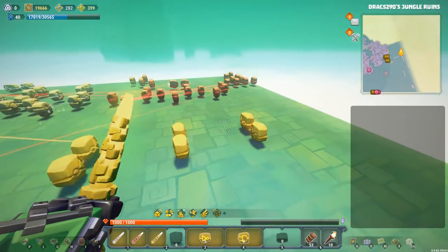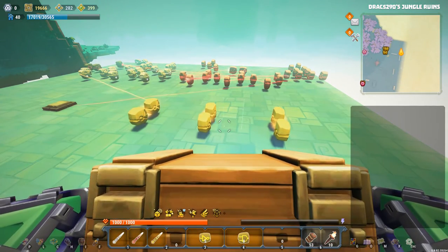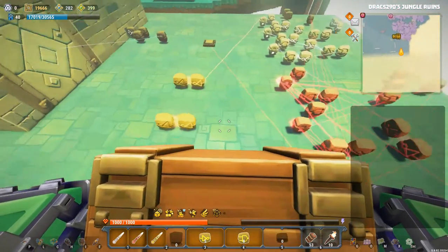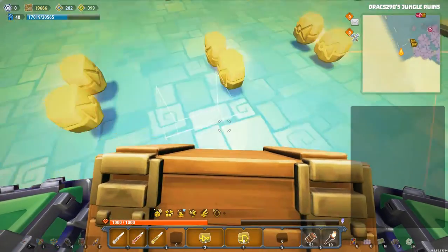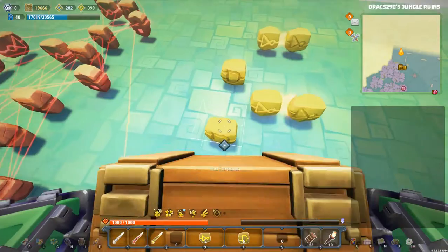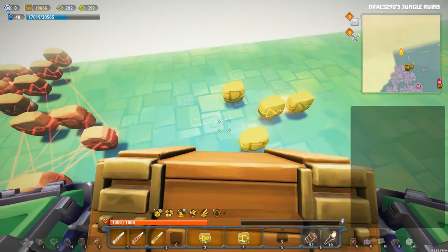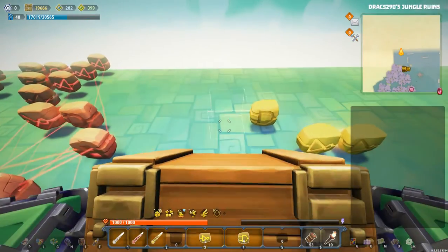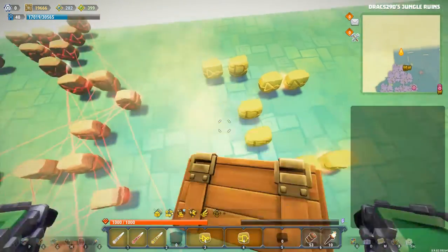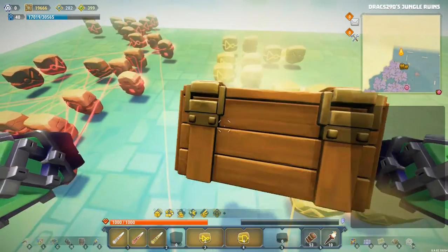These other two are a little bit more complicated. We're going to use these and do these as our XOR systems. So basically we want to go through and do these as XORs. That means they get two NOT gates each and two AND gates each. So you put down the AND gates first, just like I'm doing, and then we put down two NOT gates, 1 and 2, and 1 and 2.